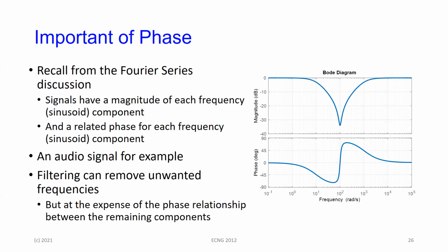Now we'll conclude with a small discussion on phase. Recall that when we have been talking about all of this, we keep insisting that the signals have a magnitude response, which is all well and good. But there's also a phase response associated with all transfer functions. Phase is almost as important as the magnitude response, because we said, for instance, in audio, if you change the phase, which is the time relationship between the signals, then the sound that comes out will sound different than what went in.